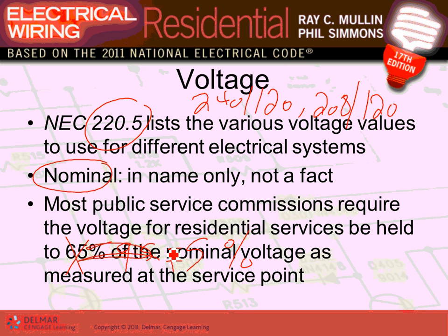So when you say 5%, then you have 1.05 times 120 or 0.95 times 120. What would that give me? Can somebody give me the calculation, guys? Grab your calculator, get it handy. If you take 120 times 1.05, equals 126. So this will be 126 volts.